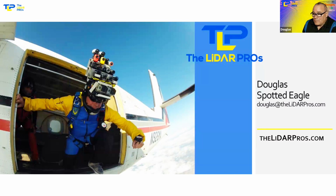Where this can run into some trouble, folks want to do photogrammetry with some types of drones, such as, say, some of the smaller DJI drones. They're not set up for automation, and so some folks say, well, you can't use that for photogrammetry then. Well, you can. We just have to manually fly grids, which means we're introducing significant amounts of human error factor when we're putting these together. So the short answer to that question of can you use any type of drone or camera for photogrammetry, the answer is yes. The longer answer is how good do you want it to be?